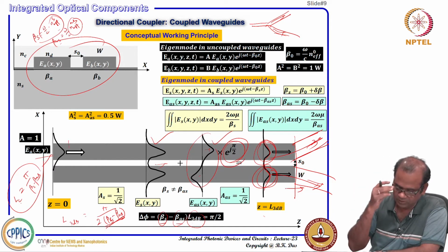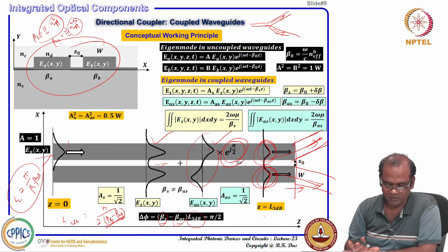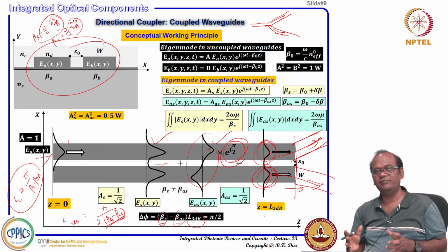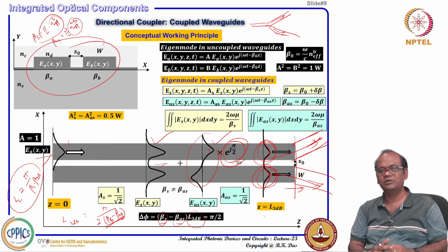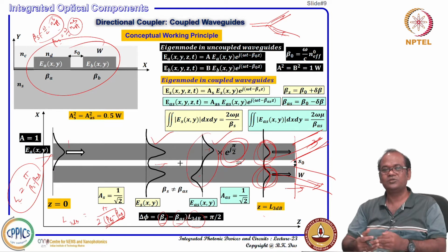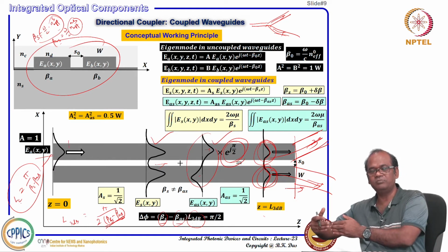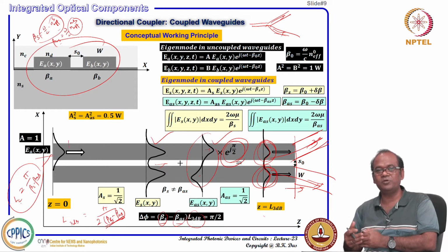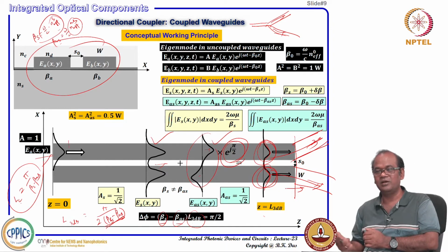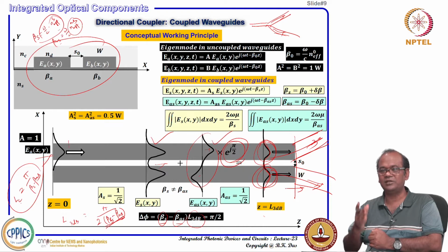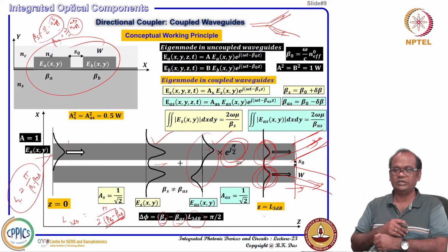Okay, good. So, we know that if two waveguides are interacting, even if only a tail reaches the other waveguide, they start interacting and power can couple through supermode excitation. As long as you maintain that type of coupled parallel waveguides, the supermodes are eigenmodes carrying energy independently. But their superposition gives a certain percentage of power in the second waveguide; you terminate there, break the orthogonality condition, and get the desired splitting ratio.